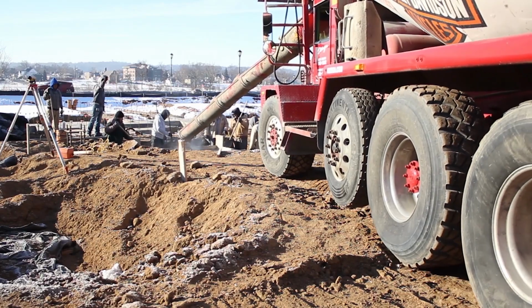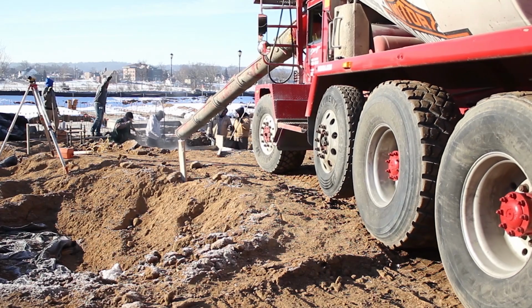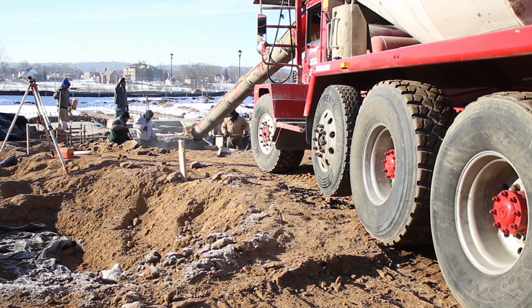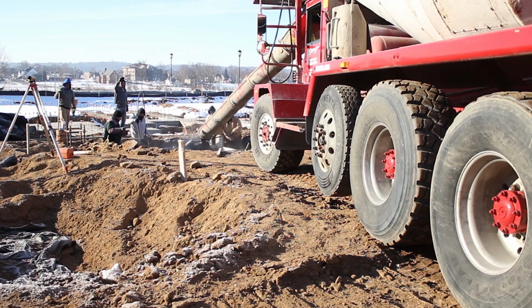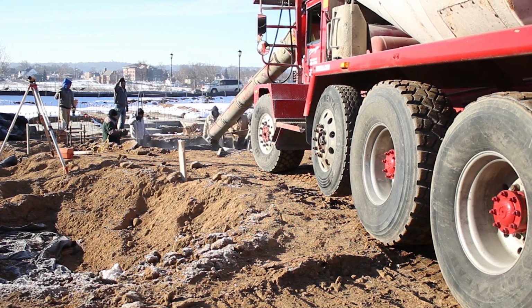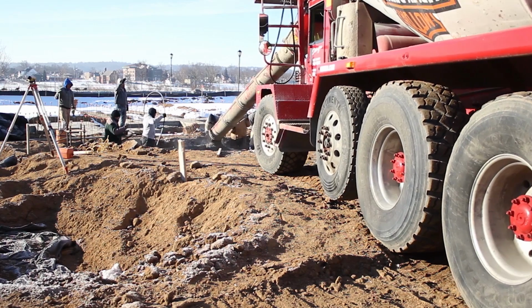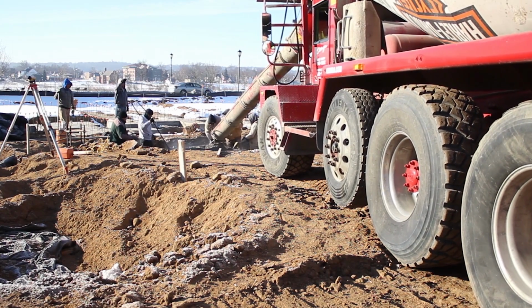Other products that are loaded directly into your mix at the plant are admixtures, or chemicals that affect how the concrete pours. Most modern concrete mixes are designed with 1 or more admixtures in them to reach desired slump and strength. Some admixtures are added on a pour-to-pour basis to account for the conditions of that day.